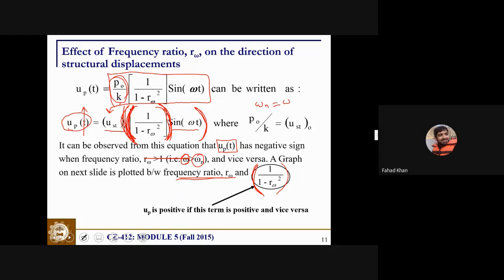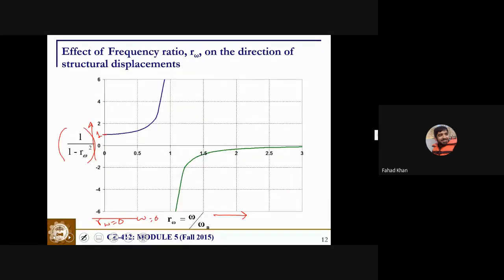What happens is that this whole term gives you this as the total particular displacement, and so your structure is moving very slowly and doesn't have any of the dynamic components to it. Otherwise, if omega n is infinity, it means the structure is very, very rigid. Even in that scenario, our omega is going to be undefined, or if we take it as 0, then our displacements are going to be equal to 1, meaning the amplification is 1.